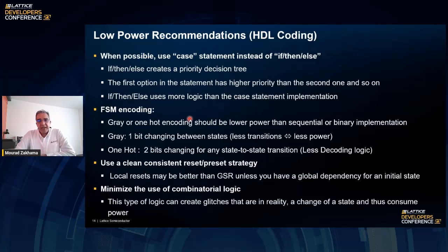So when it comes to HDL coding, the way you write your HDL code or your source code matters in terms of power consumption. There is a difference, even if functionally things may be the same. There's a difference between using the case statement and the if-then-else statement. So if-then-else creates a priority decision.